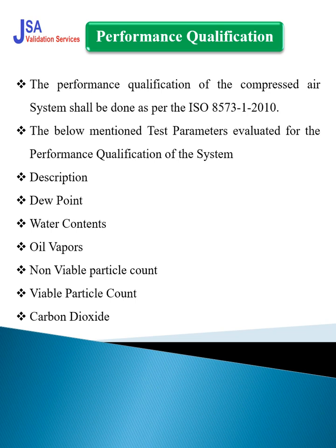these are some tests that we have to include in our test plan for the performance qualification or requalification: the description of the compressed air, dew point, water contents, oil vapors, non-viable particle counts, viable particle counts, carbon dioxide, carbon monoxide, sulfur dioxide, and nitrous oxide. Those are the basic tests that we have to include in the test parameters of our qualification plan. Apart from this, we can also test for hydrocarbons, lower hydrocarbons and higher hydrocarbons, and oxygen contents in the compressed air. Okay, so these are some basic tests that we have to perform.